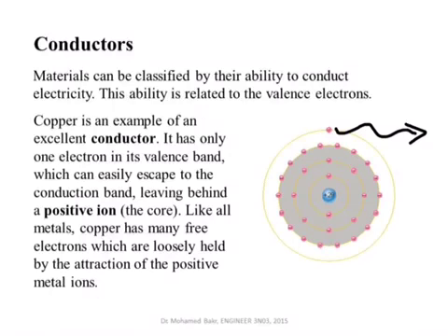So let's keep in our mind that conductors are materials that have their outermost electrons not tightly connected to the atom, and they can leave very easily if they are given very little thermal energy maybe, or even without any thermal energy. They can simply leave the atom and then conduct current. And if you apply an electric field, as I will explain to you later, the electric field will make electrons drift against its direction. So this results in a current in the direction of the electric field. I will explain this in the later slides.